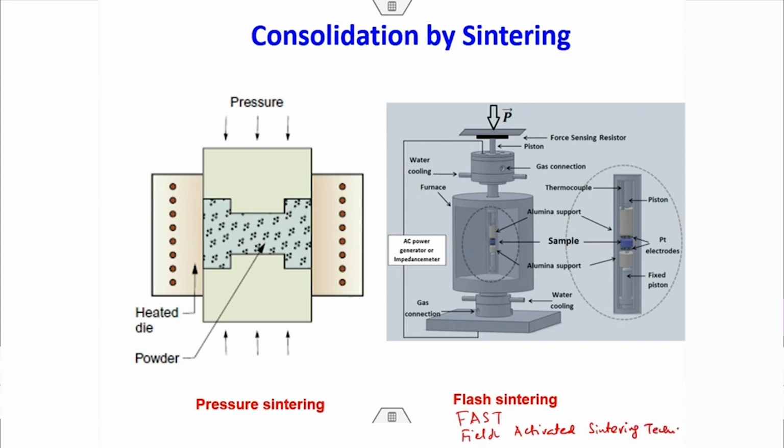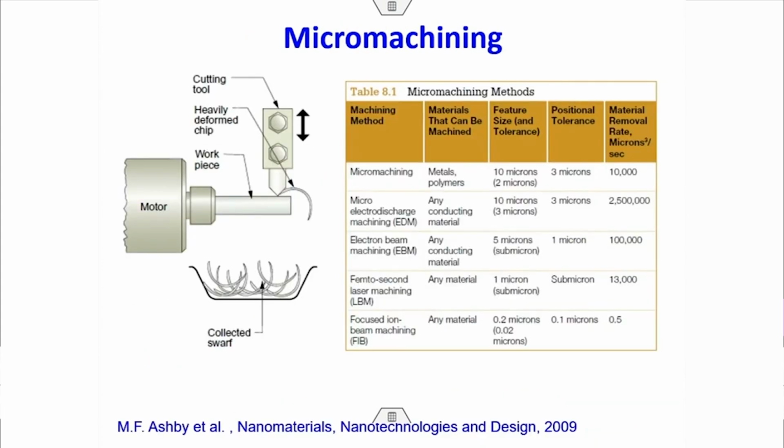Right, that is what is widely used. Then you can do micro machining, which can lead to a lot of chip formation, and because of machining, shear force is pretty high. Therefore, this leads to a lot of nanocrystallization in these chips, and the chips can be ground and made into powder, and the powder can be consolidated. So there are many machining routes.